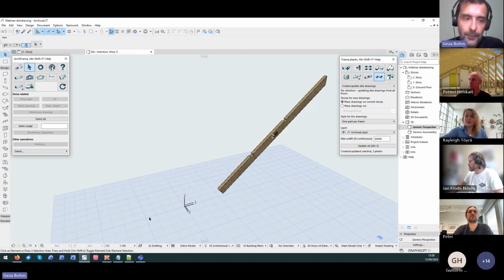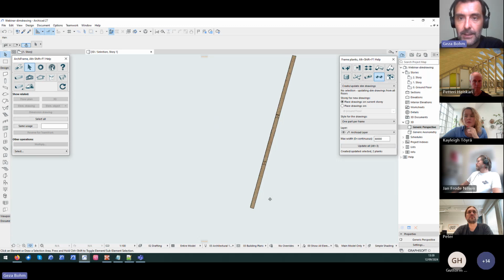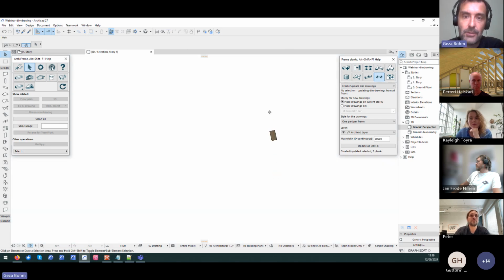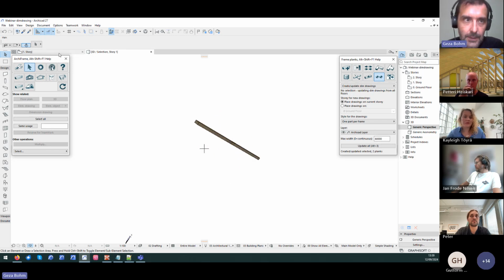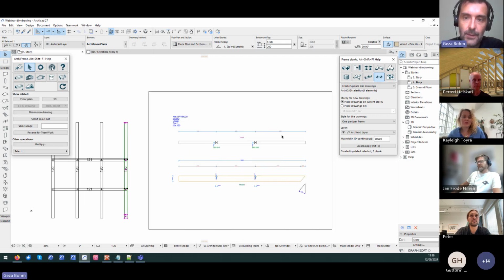In this case, if you watch it from the front side, then you will see the grooves and the angled end too. If you watch it from the top side, you will see the grooves as well and the drillings. But there is nothing special to see from here, and also from the bottom there is nothing to see. That's why the side projections are not shown. Also, the bottom projection is not shown.